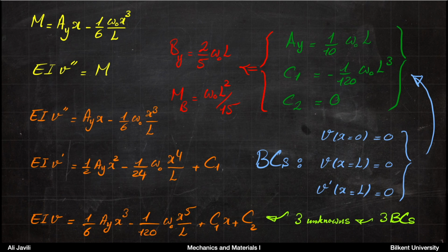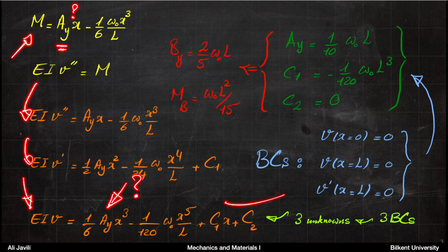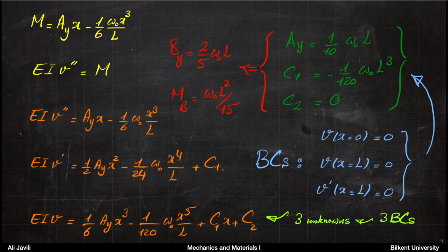And you can see in this slide everything that we did. So you calculate M based on Ay, which is unknown, but then from that, you calculate the deflection. In the deflection function, you would have that unknown, but then using boundary conditions, you can eventually calculate that unknown, and then using your additional equilibriums, you calculate the reactions at the other support. What we want to do next is to solve this exact problem using the principle of superposition. So alternatively, we want to see how we can approach this problem if we use the principle of superposition and the tables that we had in Appendix C.